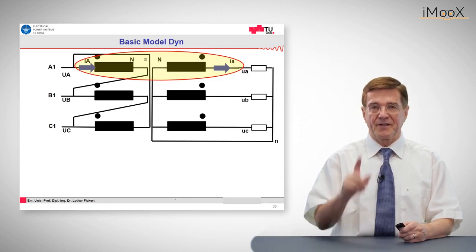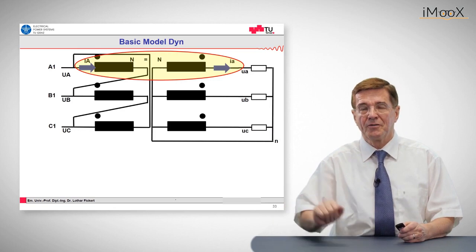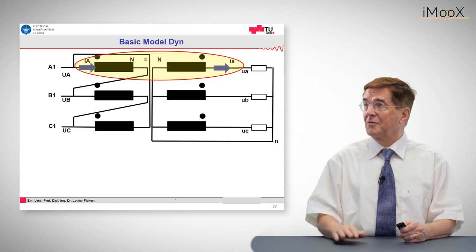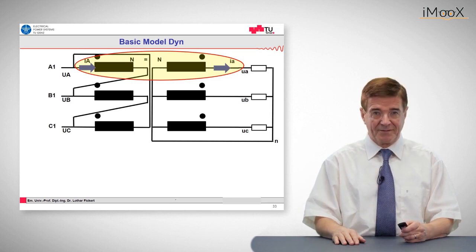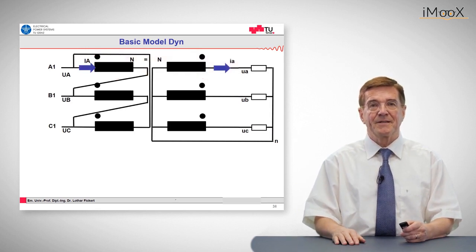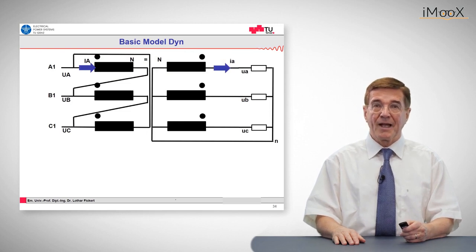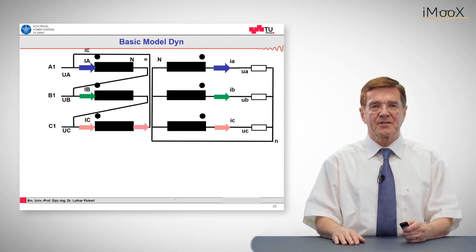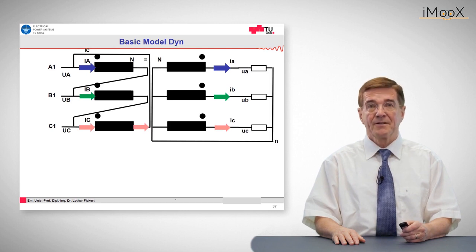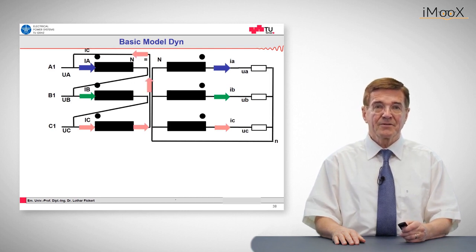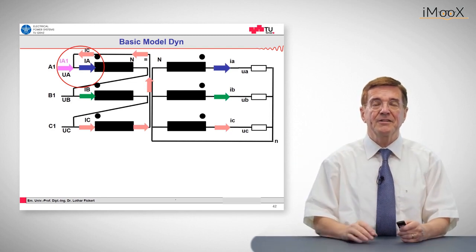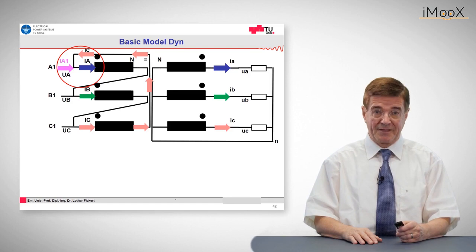So let's start again in phase number 1 with a current on the low voltage side. So the low voltage current is transformed, if the number of turns is equal, to the same current on the primary side. So the same that happens in phase A, happens in phase B and in phase C. And now let's see what the phase C current is going to do. So it comes out of this third winding, goes up to the left, and here the two currents merge and they eventually make up the real primary current.